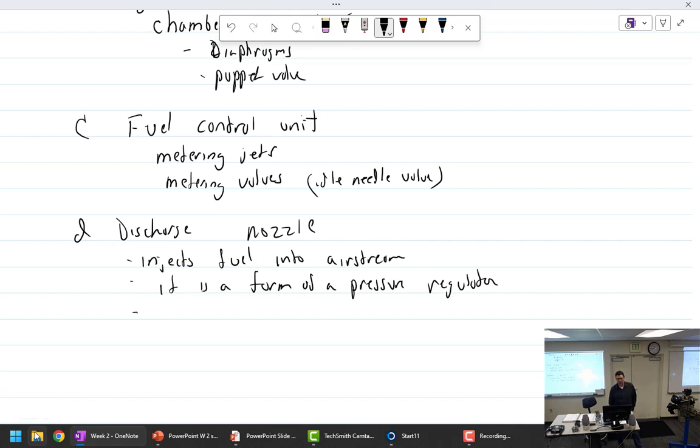And may have a shutoff spring. So you want to get a nice clean break of fuel. You don't want fuel dribbling on, because when the fuel dribbles in, the engine doesn't get a clean shutoff, and then it may want to run on a little bit and make some noise. You want a nice, that's it, shut down. So we're going to look for that in all the systems that we're studying from here on out.